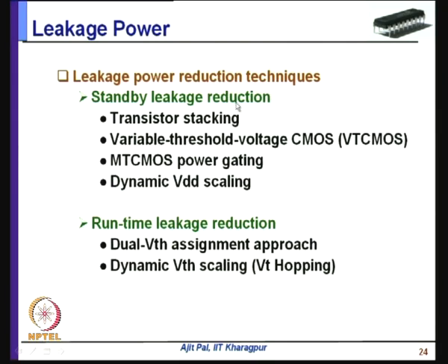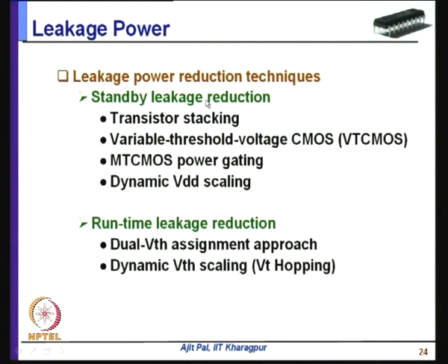Standby leakage reduction techniques can be used when the circuit is in the standby condition, that means the circuit is not in use. On the other hand, runtime leakage reduction techniques can be used even when the circuit is in operation. Earlier, since the dynamic power was a significant component, much larger compared to the static power, leakage power reduction was mainly focused on standby reduction.